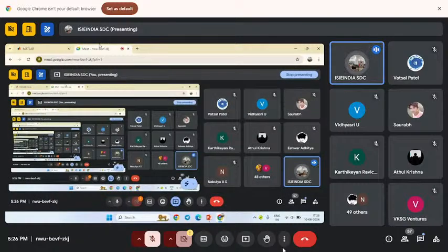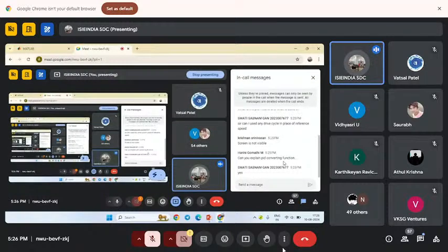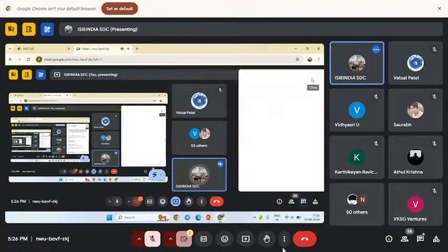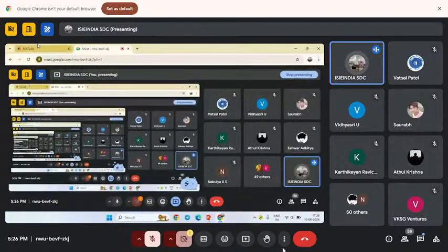Yeah, and also someone is asking me questions like you can use a drive cycle, because the drive cycle will be in velocity, meter per second. So you need to convert meter per second into RPM, and then you need to give that. And someone is asking whether I can explain the PID conversion functions. I also explained here only the conversion functions, with the KP, KI and KD values. You will get to know how it will work.